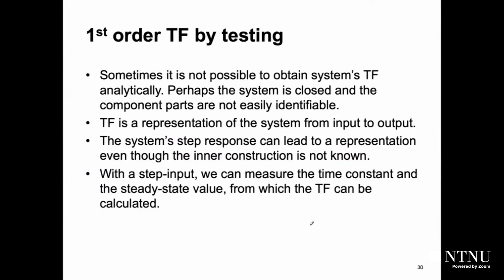Finding the first order transfer function by testing is very important. How can we get the transfer function of a first order system by testing? Because sometimes it's not possible to obtain the system transfer function. You have a system and you don't have its transfer function or a differential equation, so you can't find the transfer function analytically. In this case, we need to do a test in order to plot the response and try to find the parameters of the transfer function of your first order system.